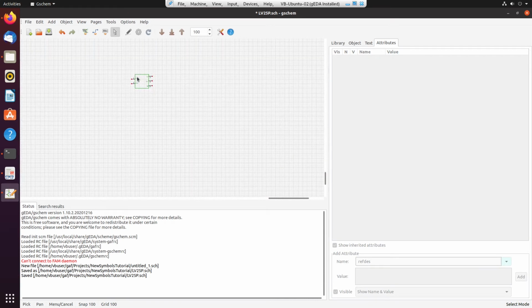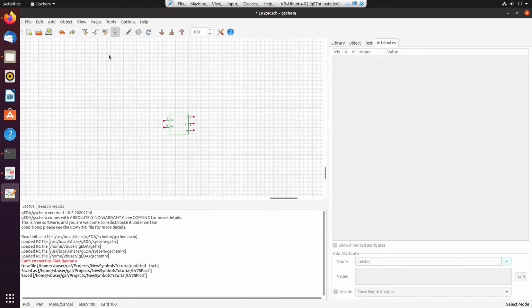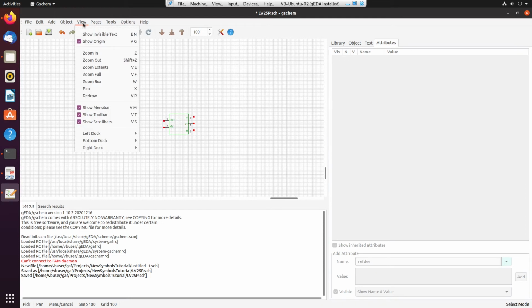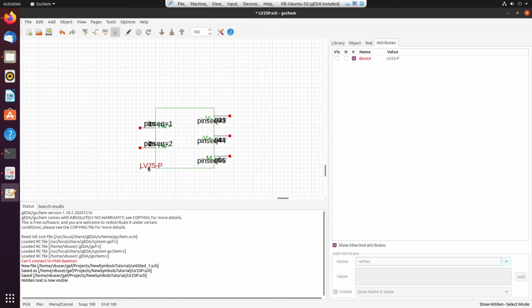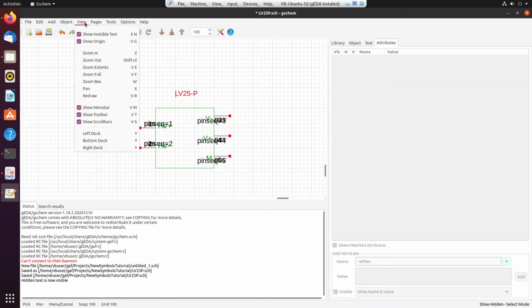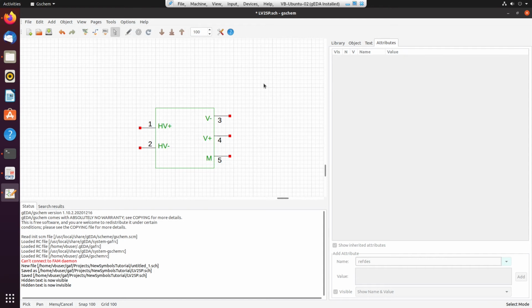So now, by the way, in case you added stuff and you wanted to see where things got added, we can enable showing of all invisible items. So for instance, this attribute that we added and we marked not visible, we can see that it's up here, and we can change this to show whether just the name or show the full thing. So that's how you see attributes or other parameters that are set to invisible by default. So then we can shut this off again.